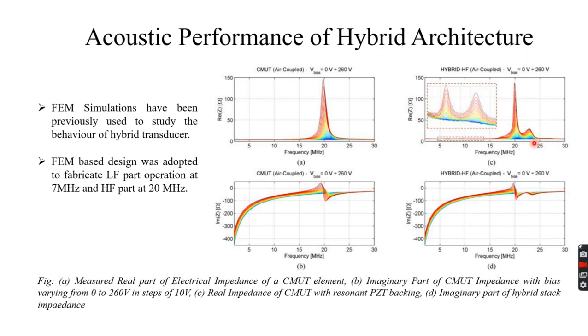And you see the third mode frequency of PZT around 22 megahertz, which is also seen in the reactive part. So that's how you have two distinct frequencies for these transducers.